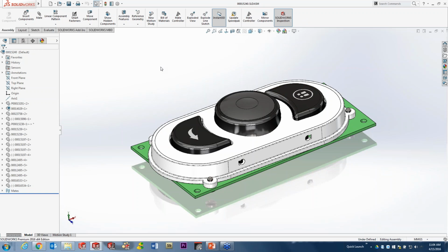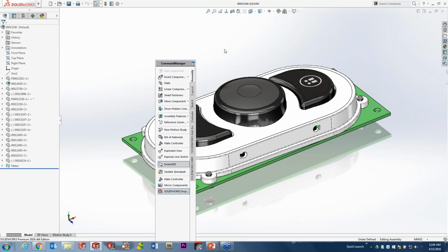So here we have SolidWorks 2016, and of course you can see the color changes that we have across the top. This is something, again, I'll detail as we get going. Now, for a lot of users out there, you've had situations where you're modeling quick and you're grabbing buttons and accidentally pick and drag, and this type of thing happens. And that's our command manager getting detached.